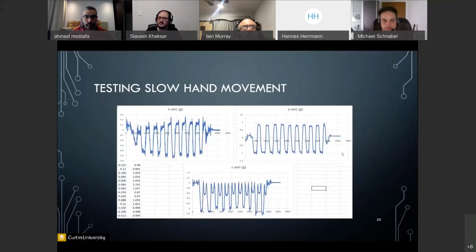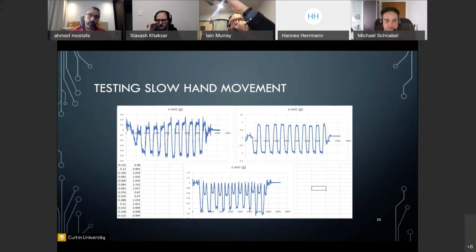And quick jump in here, Savash. One of the key things to take away from this is the fact that sensors are not nice, perfect devices. So we need to look at the signal conditioning and linearization in a critical manner. Most sensors will not give you a straight line reaction or a linear relationship to what they're sensing. There will be some curve or some sensitivity, might be light sensitivity, or could be temperature sensitive, things that will make our line, instead of being nice and straight, where we can say at this point it matches 30 degrees C, it'll actually be more of a curve. So you'll get a more rapid change at higher temperatures, for example, than you do at lower temperatures. So one of the things you have to be able to do, and this is normally done and published through the data sheets, is apply a formula to the raw readings that you're getting to linearize the output.